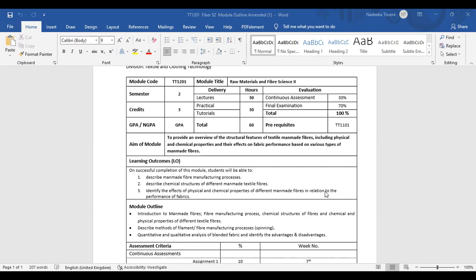During different spinning processes, carding, roving, all these things, they take these non-continuous fibers with different lengths, align them, twist them together, and then make a continuous yarn. Understand? So when you take a natural fiber, there is a collection of short fibers twisted together to make a continuous yarn.